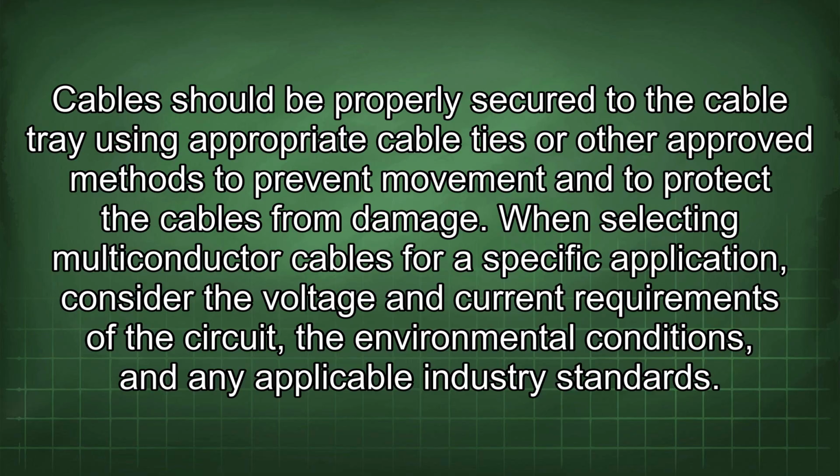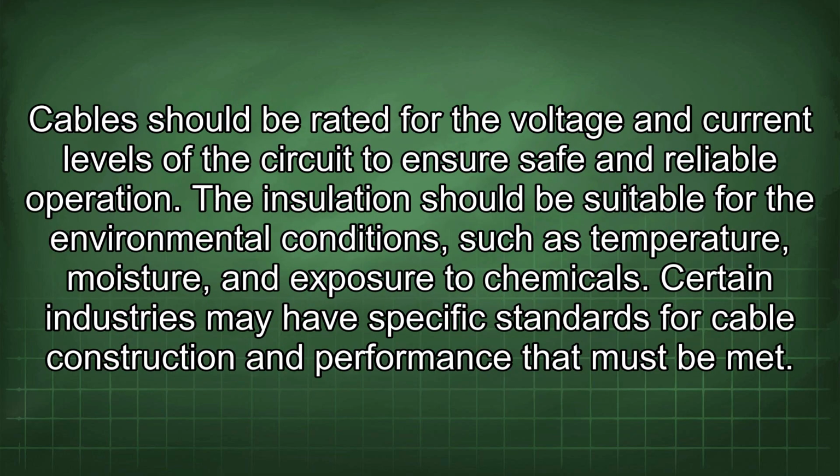When selecting multiconductor cables for a specific application, consider the voltage and current requirements of the circuit, the environmental conditions, and any applicable industry standards. Cables should be rated for the voltage and current levels of the circuit to ensure safe and reliable operation. The insulation should be suitable for the environmental conditions such as temperature, moisture, and exposure to chemicals. Certain industries may have specific standards for cable construction and performance that must be met.